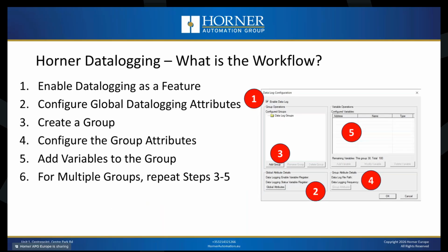What is the workflow like? First, we enable data logging as a feature. Then, we configure the global data logging attributes. Then, we create a group and configure the group's attributes. Then, we add our variables to the group. And finally, for multiple groups, we repeat this process as needed. Now, let's take a closer look at each step.